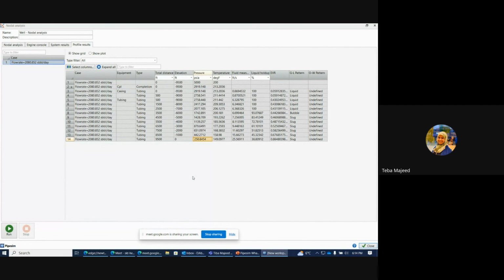So we take into consideration the effect of the wellbore components on the flow. For example, the tubing ID, if we have water cut, etc. With the well configuration, with the fluids being produced, will the fluid flow from the reservoir, from the bottom of the well to the wellhead or not? So this is actually what we need the steady state simulators for.